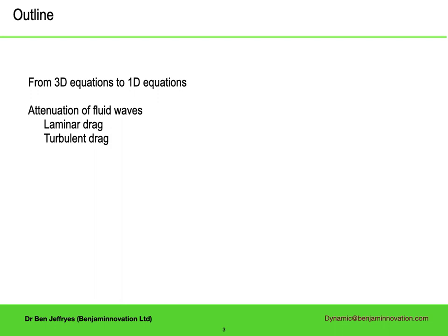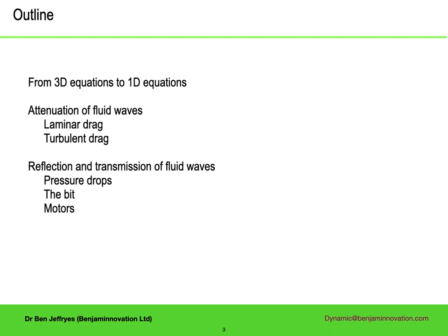This is an outline of what you will learn. Firstly, an explanation of how to derive the necessary one-dimensional equations, followed by a discussion of the attenuation of fluid waves from both laminar and turbulent effects. Then a few slides on reflection and transmission beyond the effect of impedance changes, particularly those from pressure drops of various kinds. And finally, how over the long distances of well bores, the acoustics of the fluid in the pipe couple to the fluid in the annulus.